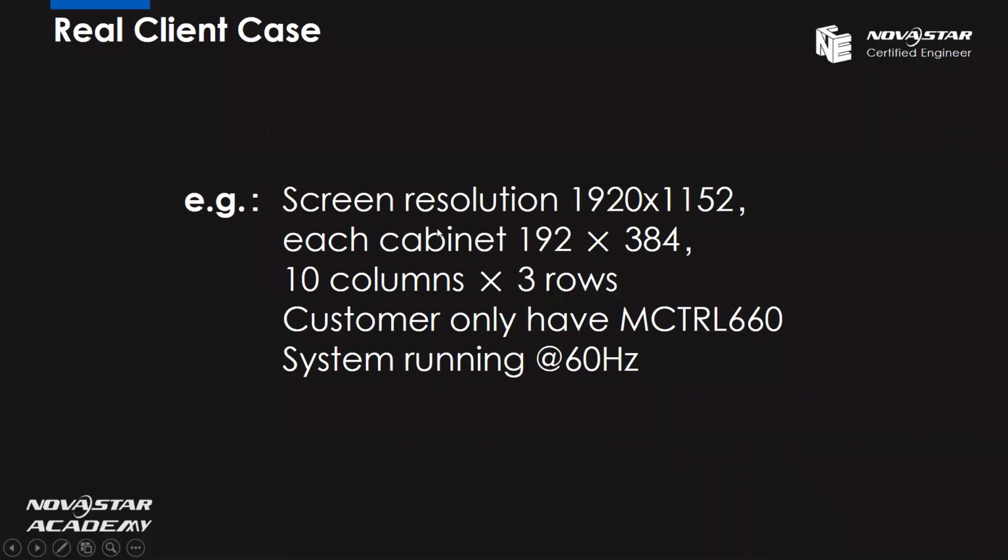The screen resolution is 1920 by 1152. And each cabinet's resolution is 192 by 384. And the customer has 10 columns and 3 rows, and they only have one M-Control 660. And the frame rate is 60 Hertz. So here, the question is, how can we finish the screen connection and how can we finish the cabling?